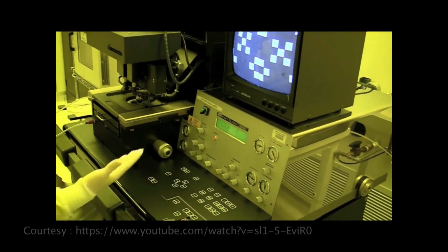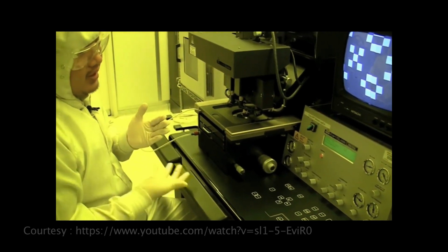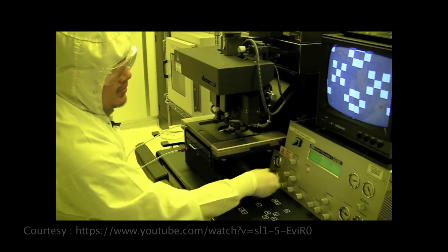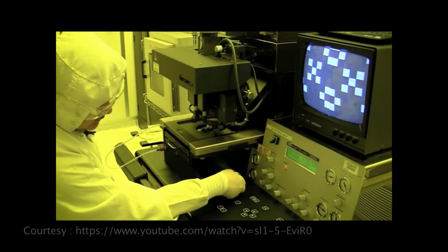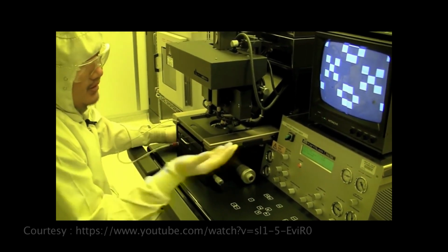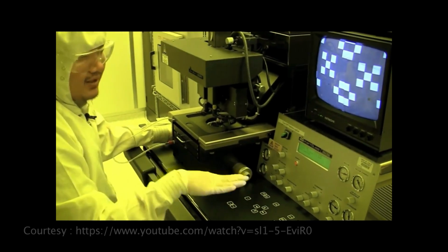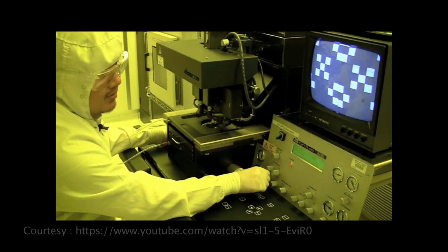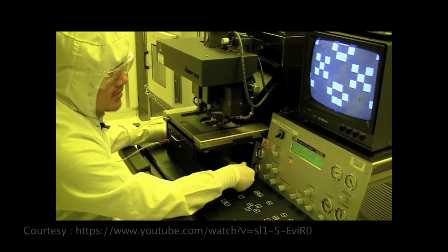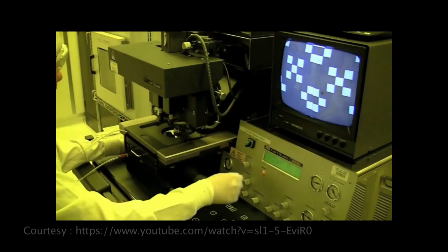So what you would do is the same thing as in backside alignment. You would align the alignment marks on your wafer to these right here. You can see that if I move this, these knobs always control the substrate. So when I move this, you can see that this has been moved. So you can tell that's the actual substrate moving, not the mask. So you try to focus it, and you're trying to find your alignment marks and align them to the features.